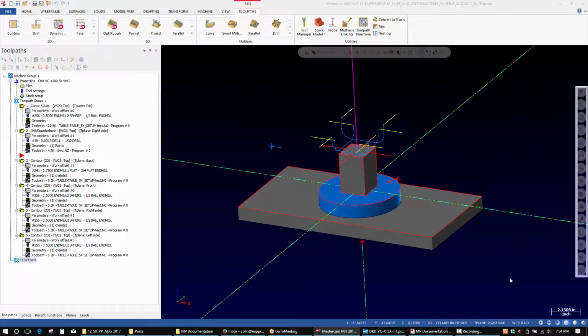Today we're going to be talking about making edits to the Generic Fanuc 5x mill post and looking at a couple of things. We're going to look at where output comes from. So what are the post blocks that are responsible for generating output from the post, so that we can know in general where to make edits. Then we're also going to take a look at formatting, both for changing the prefix addresses for strings and the numeric formatting portion of the variables, so that we know how to change that.